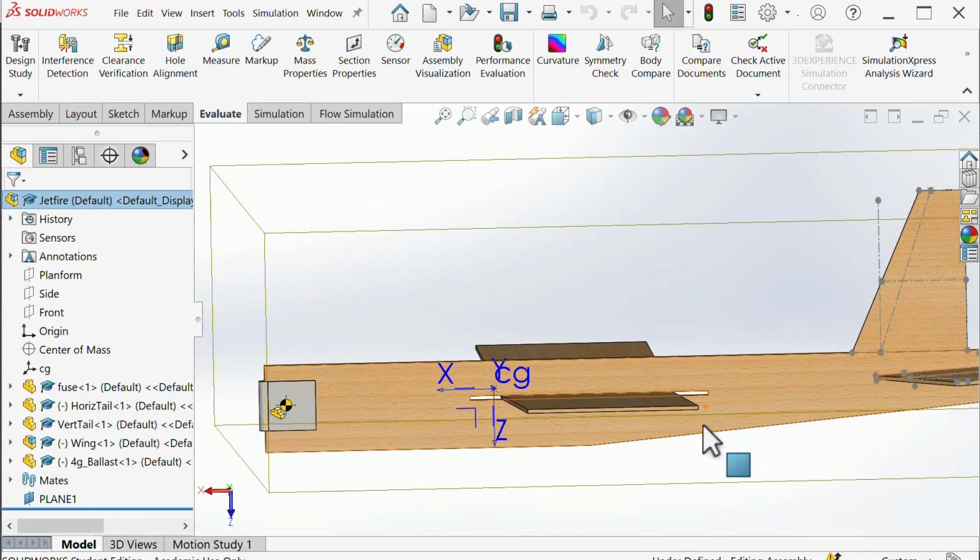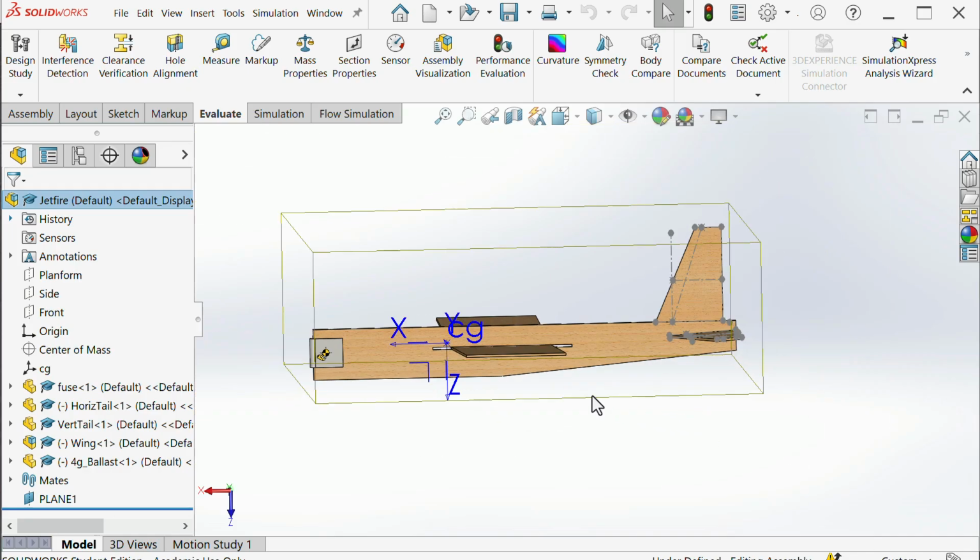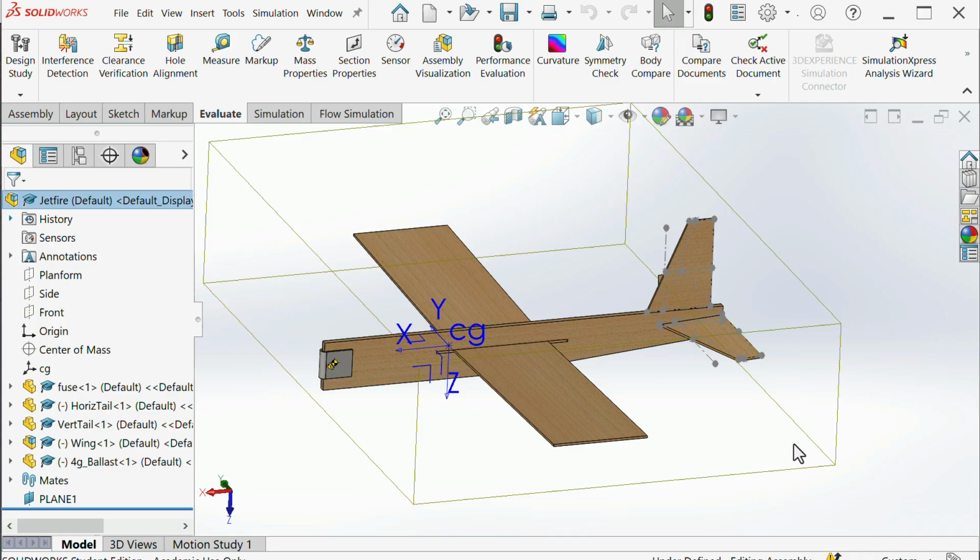You can move the wing. You can change the incidence of the tail, right? If you made this tail incidence even more negative, even at this forward CG, it would want to trim at a higher angle of attack. But then, of course, the rules of your contest are a little bit different every year. But you can change things about the wing, the wingspan, the taper ratio, and then of course, you could always change the tails. It doesn't have to be this big.